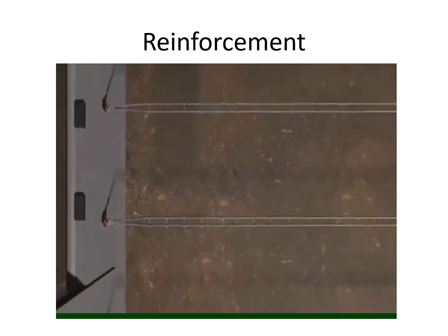The basic concept is that for the failure of the wall, the wall should go to this side. So for the wall to go to this side, it needs to pull the reinforcement also. But the reinforcement cannot be moved easily, because it is under friction with the earth. So the failure will be avoided. Failure is avoided in this case.